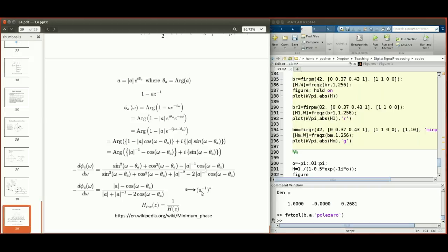If we replace it with its reflection with respect to the unit circle, then the absolute value of a is going to be larger than unity. So if a is lying within the unit circle, this particular zero of the transfer function lies within the unit circle, then reflecting that zero with respect to the unit circle is going to increase the group delay. Which means that if you want to minimize the group delay caused by a particular zero, you would like to have that zero stay inside the unit circle.